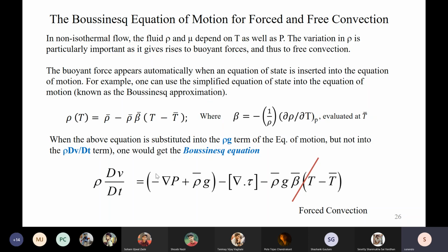So it is the pressure force, most likely in conjunction at times with the gravity force, that is going to predominate. And this is the viscous term, which would obviously be there. And in forced convection, you also have to consider the velocity, the convective transport, as well. So this is to be kept in mind.